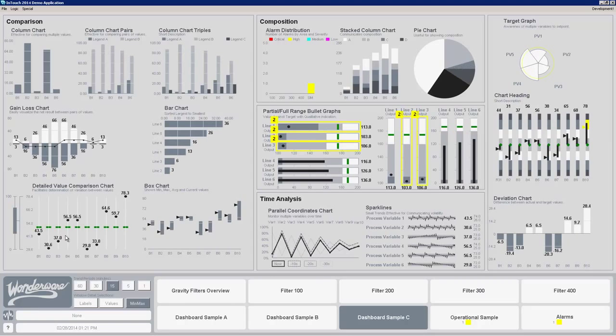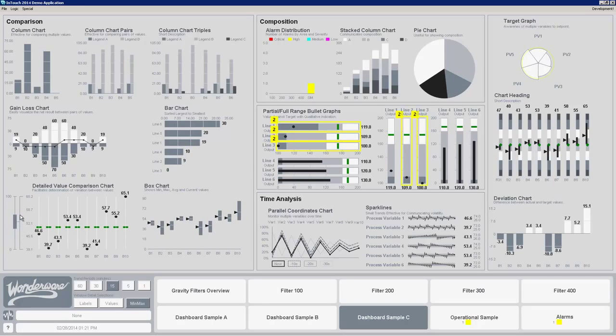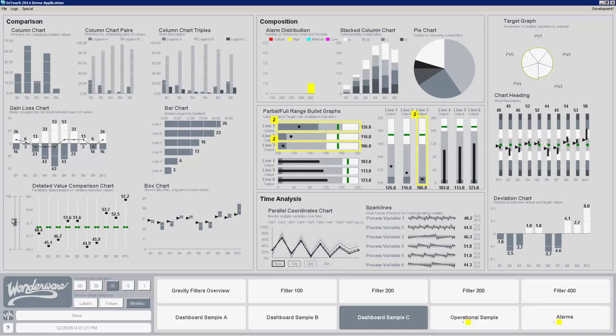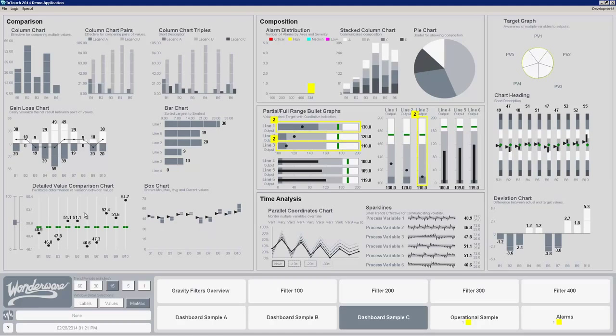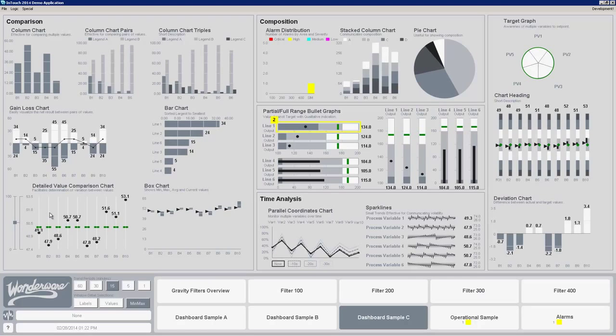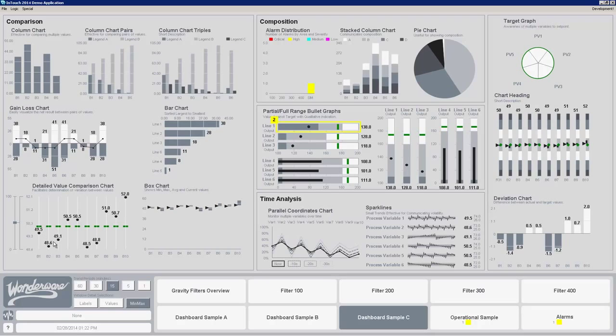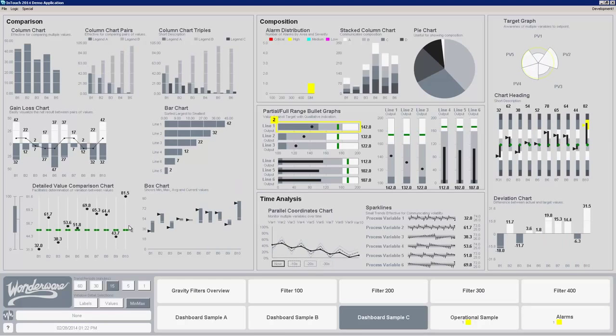What this one is intending to do is show you a variable range, or it's auto scaling. So this is the min and max on the far left here, 0 to 100, and the auto scaling range is just that thick part here of what's being shown. So this is kind of zoomed out, if you will, so that you can start to see detailed differences between values. And the green lines here are kind of the expecteds, or the set points. So how am I deviating? Where are my biggest deviations from norms? But you can turn the set points off if you don't want.